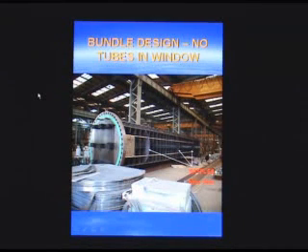span of the tube to minimize, again, cross flow vibration, which is caused by vortex shedding of the flow as it goes across the tube. The longer the unsupported span, I don't know if you've ever encountered a flagpole in a wind. It's very interesting to see. You'll occasionally see that the flagpole will start to vibrate, and it'll have different node points depending on how it's vibrating.